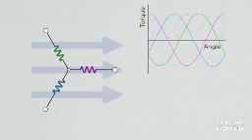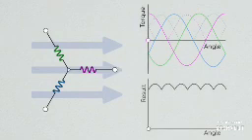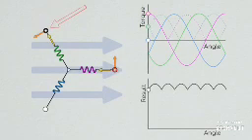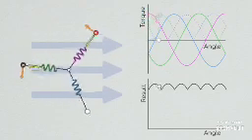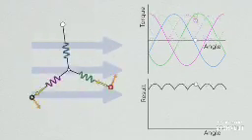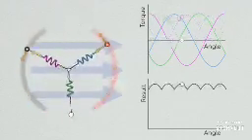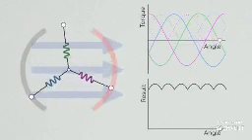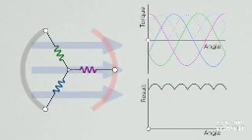If we play through the rotation of these coils, showing at each point which node needs to connect to ground as indicated by the black ball, and which needs to connect to high voltage as indicated by the red ball, we can notice a trend. The nodes only need to connect to the electrical circuit when they are within 60 degrees of parallel with the magnetic field. And to produce a counterclockwise torque with the wiring as shown here, it will always connect to ground on the left and power on the right.